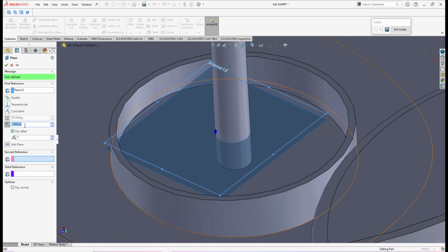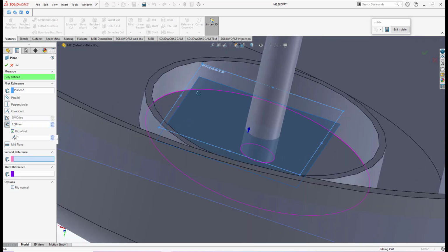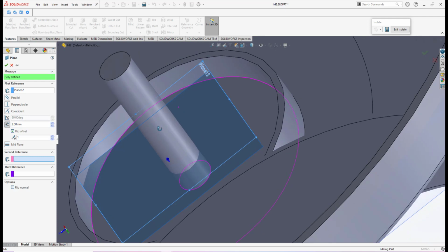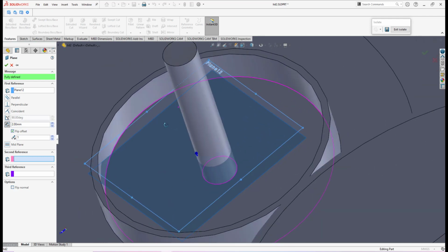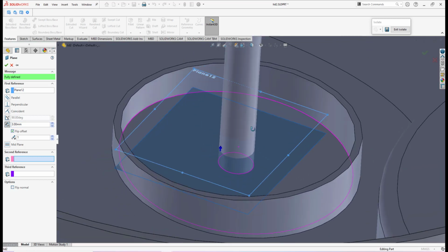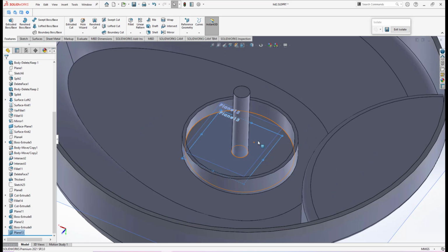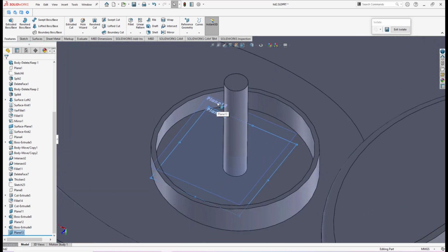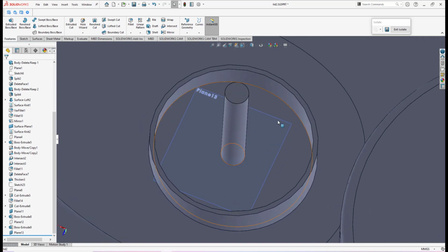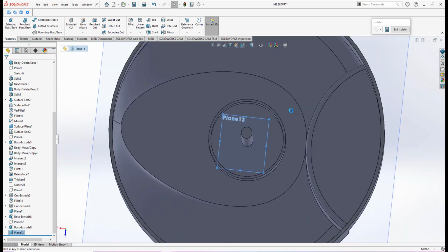Let's go for 2 millimeter for where we will place the rib. Let me go for 3. Let's go for 3 for the location where we create our rib. So then I click OK. Before that, let me hide Plane 12 here, so that we have Plane 13 here. So this Plane 13 will be where we create the rib.